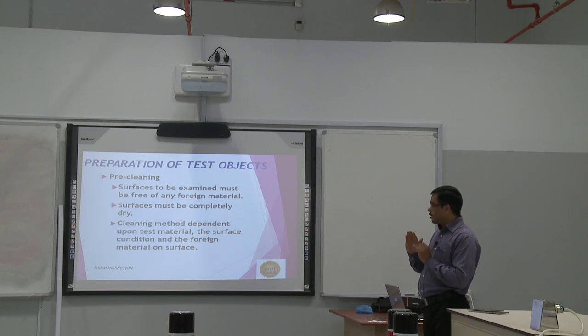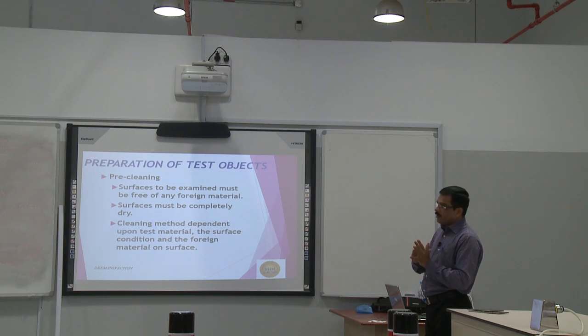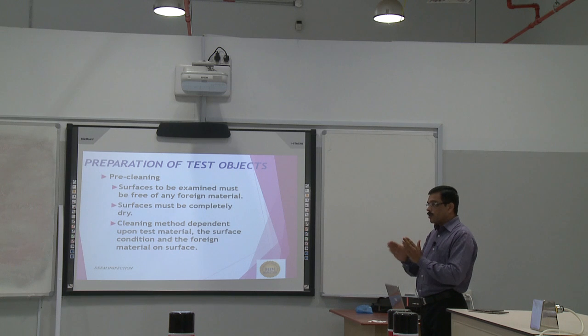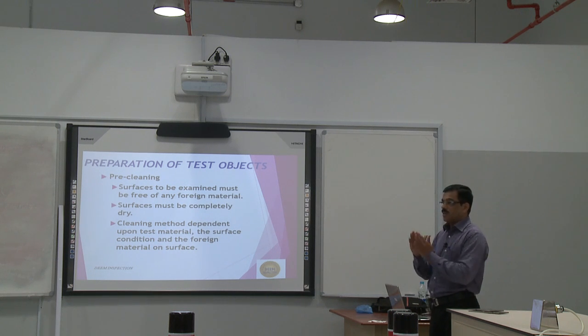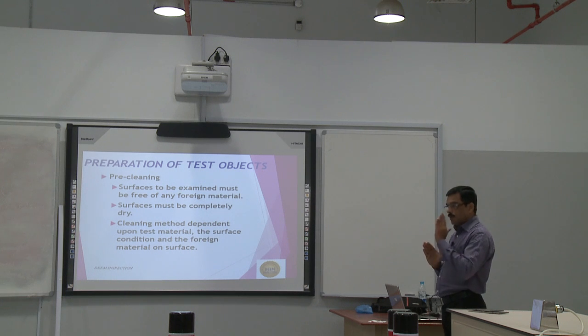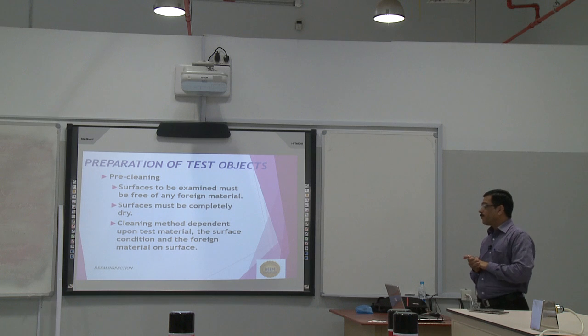If some manufacturer is selling, and we are giving more time, suppose more than 20 minutes, there may be a chance of drying, so we will do a little bit again. We have to apply penetrant because we shouldn't give the penetrant a chance to dry. So up to 20 minutes is okay. If you are giving 40 minutes, then after 20 minutes we will reapply some penetrant to keep the wettability. So whatever dwell time we give is minimum, not maximum.